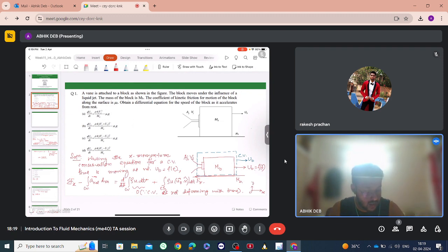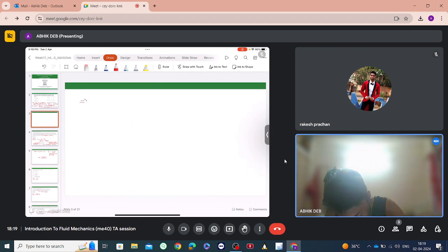So the friction will act opposite to the considered positive x direction, that is, along the negative x direction, and the friction force Fr will be equal to mu b multiplied by mb into g. Mb into g is the weight multiplied by mu b, which acts in the negative x direction. So we will have to write it as minus mu b mb g.